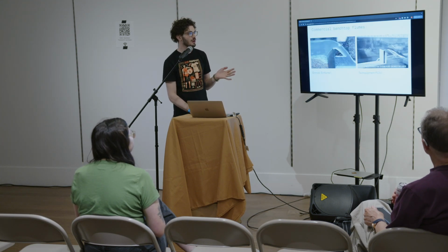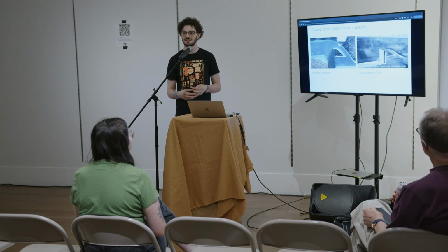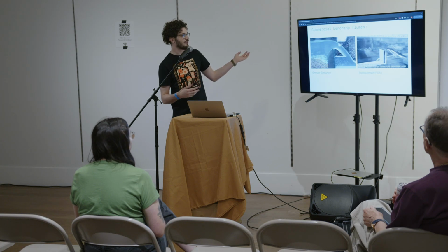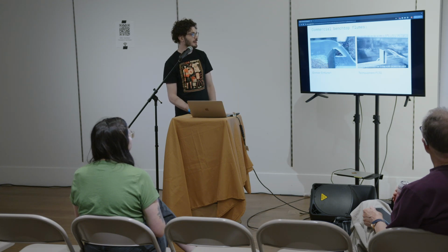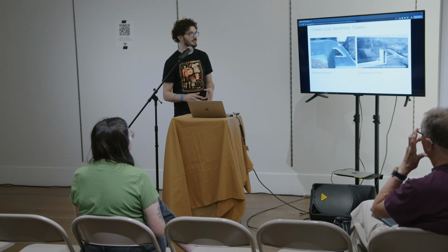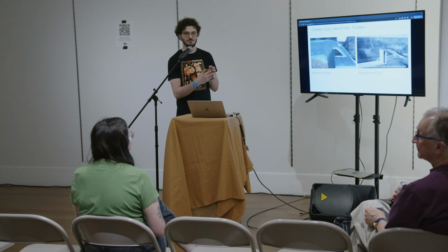When we looked for small scale flumes, like desktop flumes, there are some available, but they're almost all made for education, as demonstrations. The type of thing that you might use in a college fluids lab to learn about the flow over a weir or sediment transport, like this sand moving across the weir. These are roughly the right scale and size, and they even have the right flow rates, but they don't have the other type of characterization that we need to be confident that the flow is uniform and has low turbulence, and they're also really expensive.